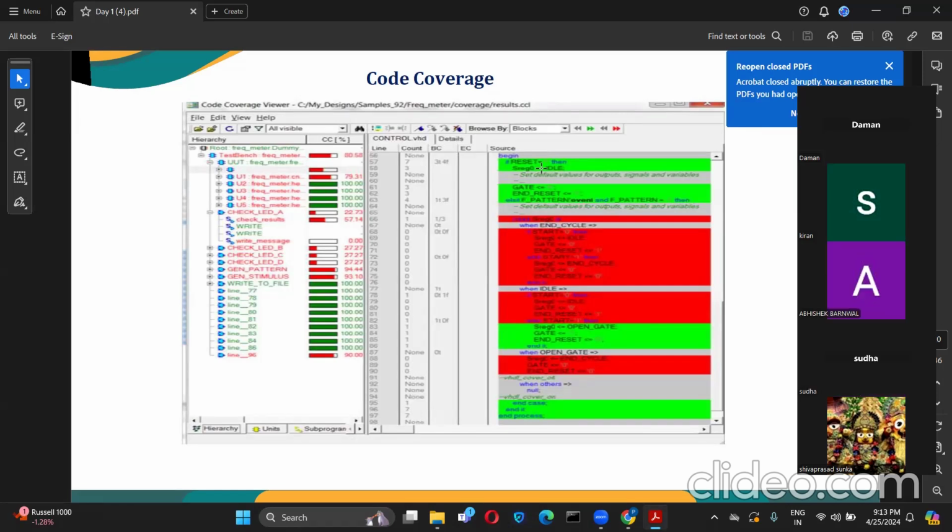Functional coverage is about the different functionalities of the design, whether they are executed or not, which we can check via functional coverage. It is design specific. And how much RTL code is exercised by a given test suite, we can check using code coverage. Correct. I am feeling so good to hear all the responses from you.